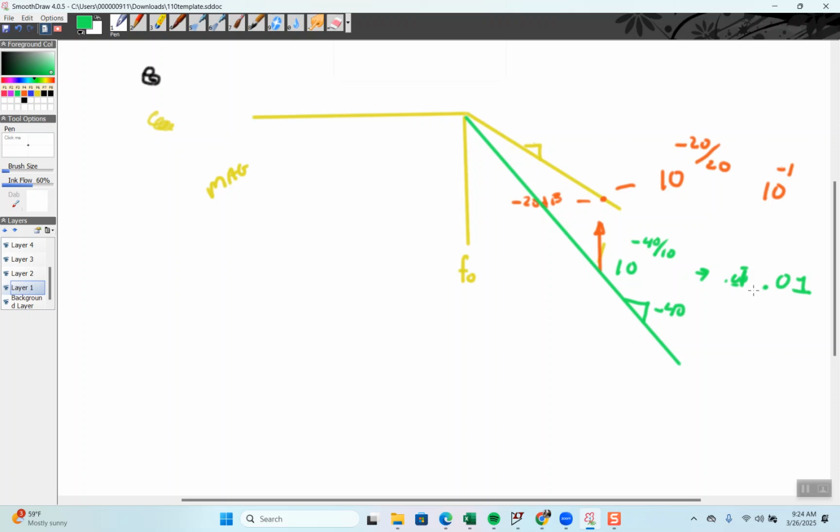How do I get the second order? Well, in some ways, you've already started to do this. So here's first order, and I'm just going to use a buffer, okay? No gain. You need this because as soon as I hook up a load, it affects the resistance, and then your cutoff frequency is off. Really what it does is it isolates whatever you're hooking up from there. All right, I want a second order. Well, just put it there, right?